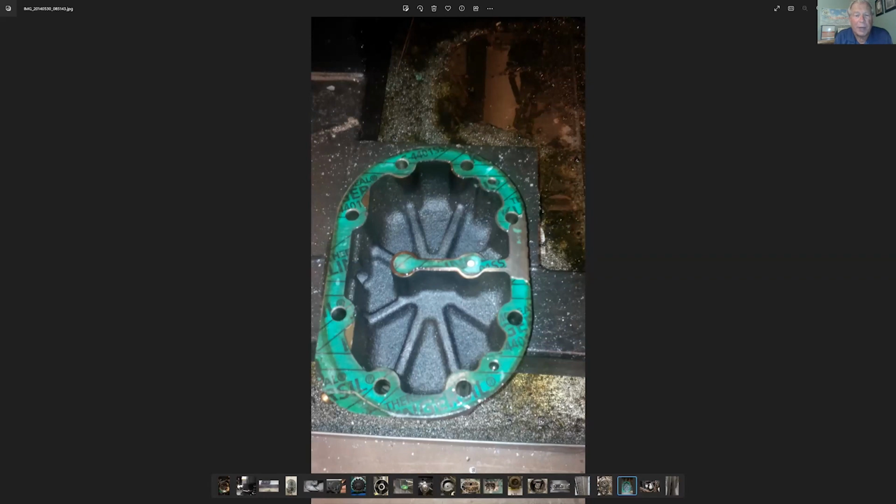And that's one of the things when they tear a compressor apart, they'll check to see, especially if they can tell the gasket's been changed, and they usually can. But just a very thin film of oil on that, clean before you put it on, put everything together, and then the proper torques with the proper cross pattern. And it's important to get into the different guides for the manufacturers, right?